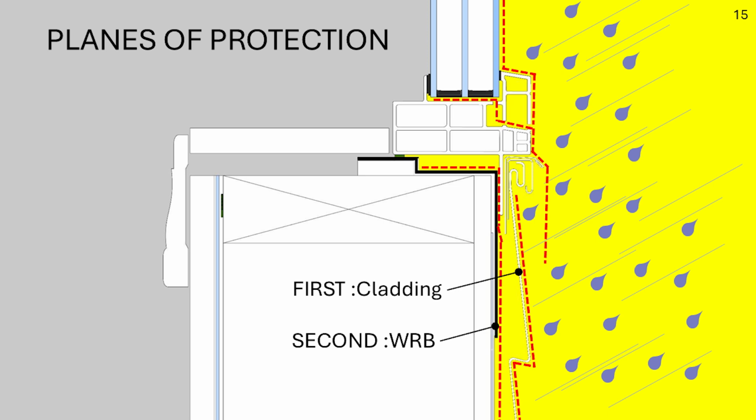So that same principle applies that if the water gets into the rough opening, we need a good airtight seal here, a back dam or a slope seal, or something to stop the water from going through, but more importantly, something to stop the wind and the air that's out here from passing through and coming into the building. Because if the air can pass through, it can easily carry the water back in. So it's all about stopping the air leakage.